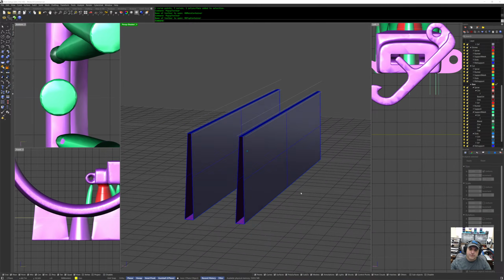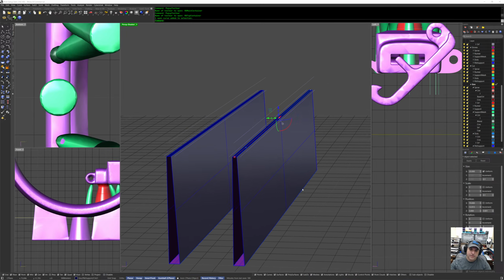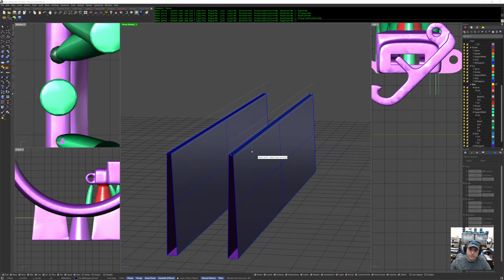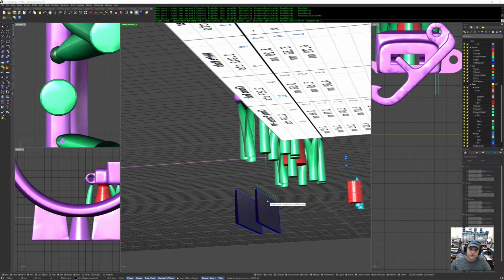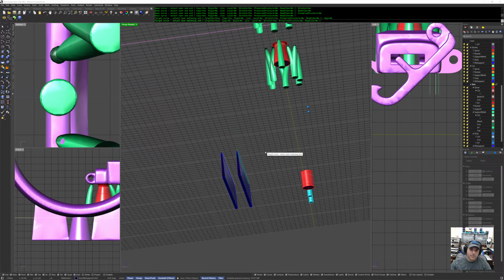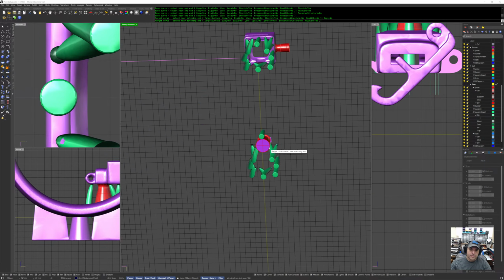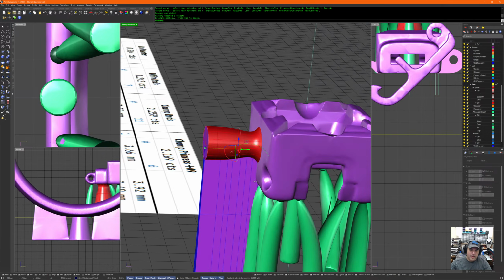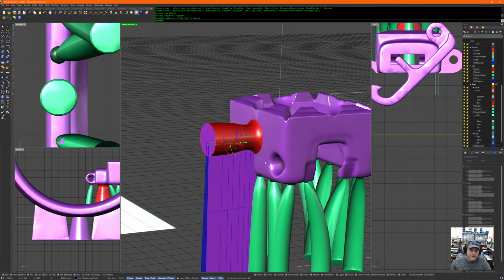Everything else will be. So I could just grab this one curve because everything else has history on it right now. Just do a flow regular with stretch. I want to go from there to without copy. There to, and then grab that iso curve I pulled out. And now it flowed it all the way to the end.